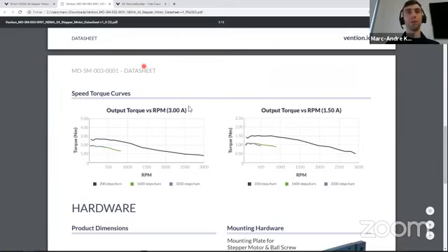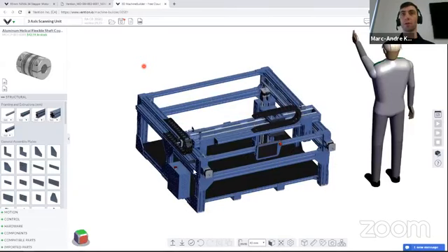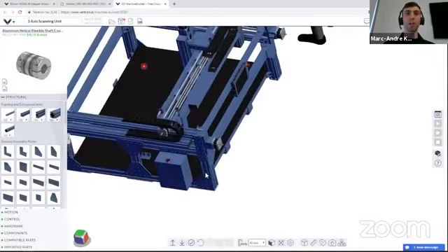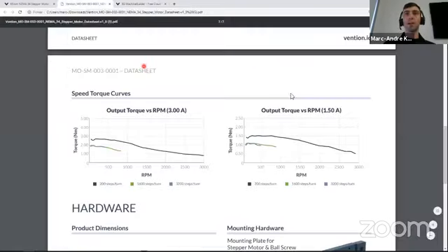The difference between those two is that for our axis here, going back to the design, for our x-axis, we're going to use one output to serve those two motors. Looking at the machine motion, we have 3 outputs. One is going to go to each axis, which means that the x-axis is going to be split in 2. So going back here, it means that we need to use this 1.5 amp curve. We can double check it. So we have 0.16 Newton meter and 300 RPM. So we're still way under those curves.